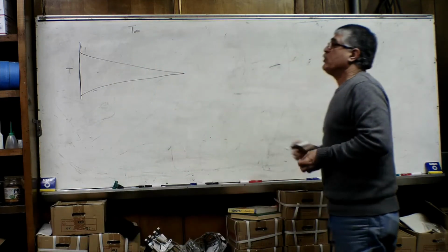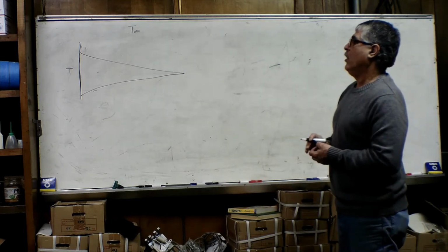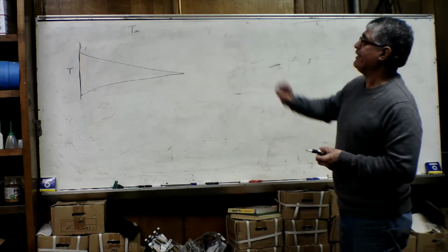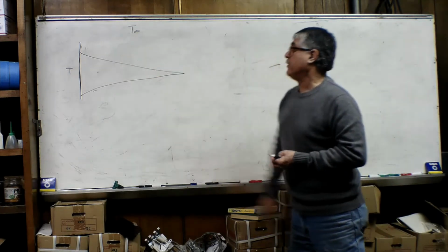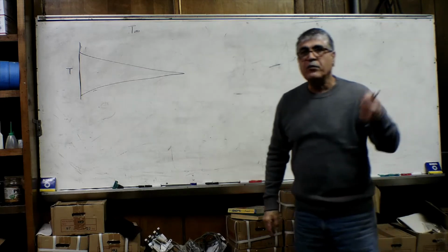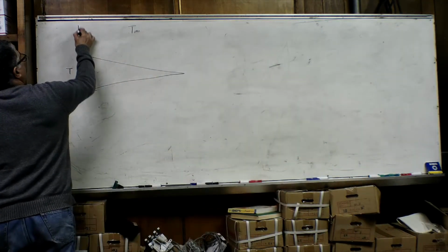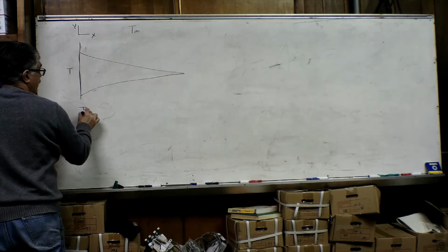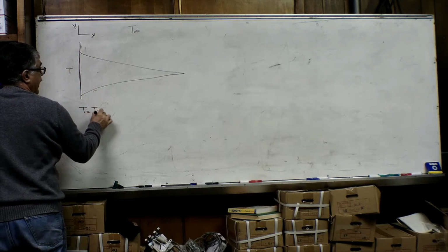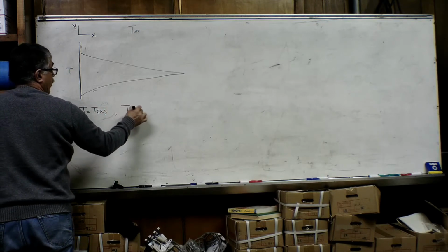And our assumption here is that our transversal thickness is a lot smaller than our axial length. So what does that mean? That means that our temperature will be a function of x rather than a function of y.